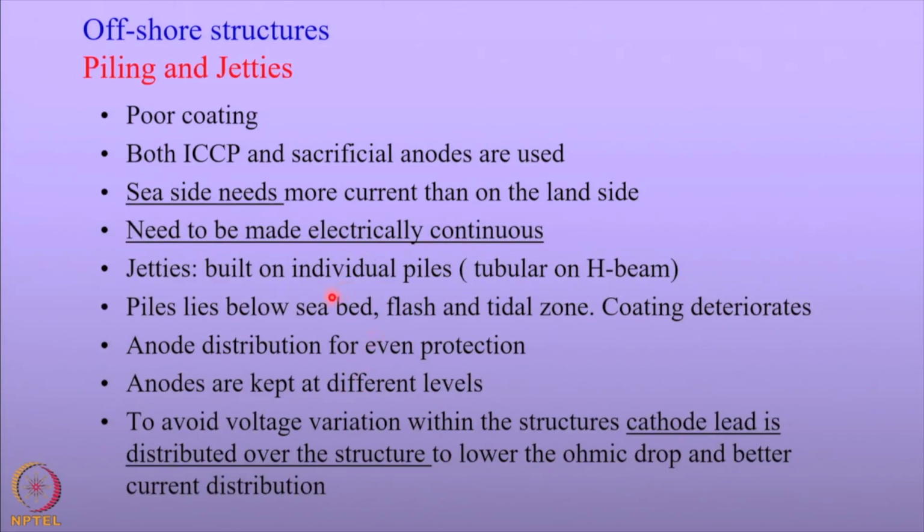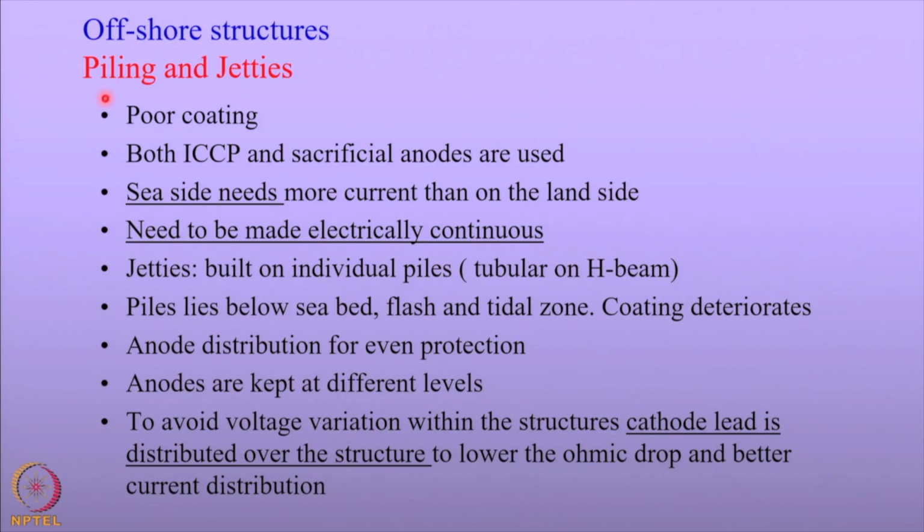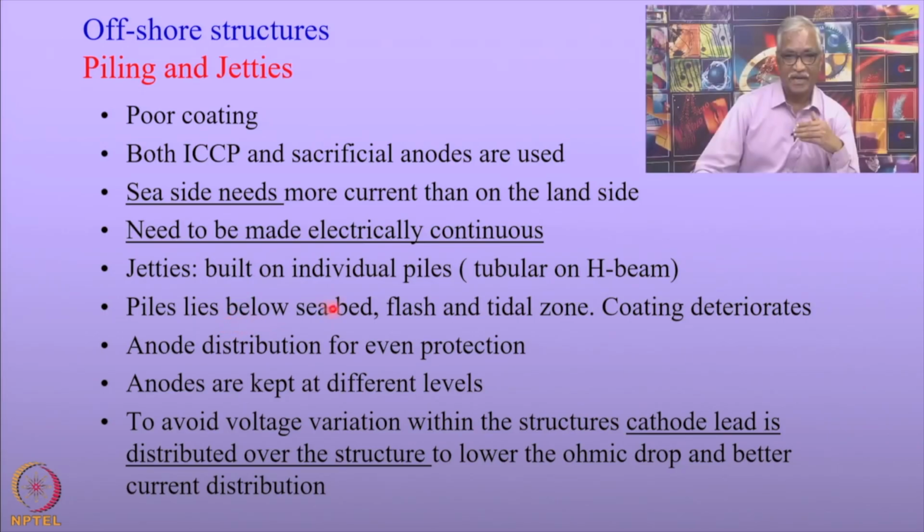In the offshore structures, we also have piling and jetties. Over here also you go for good coatings; poor coating is a cause of concern. One of the problems in the piling and jetties is that when you have splash and tidal zones, the coating deteriorates because of continuous splashing of seawater actually.